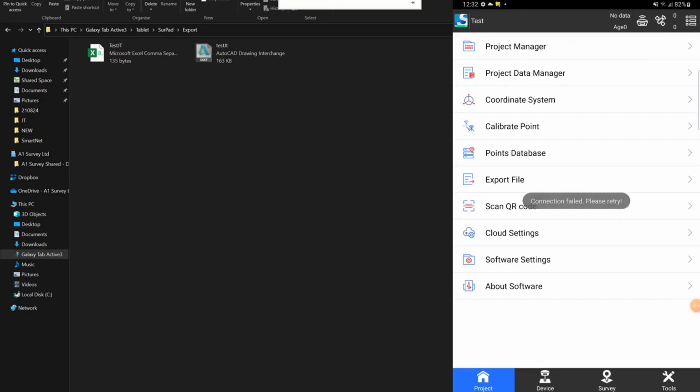Today's video we're going to be going through exporting CSV and DXF jobs off our controller. So you've got the Surpad software open up here. I've got a job named test. I've got a couple of points on it that I want to take off.